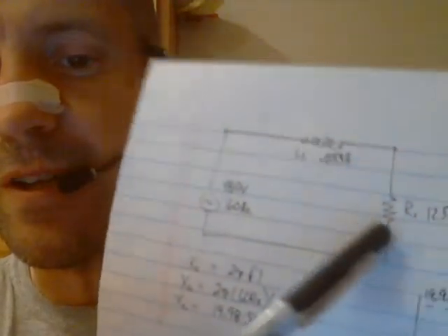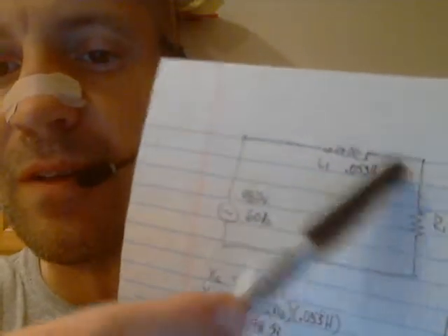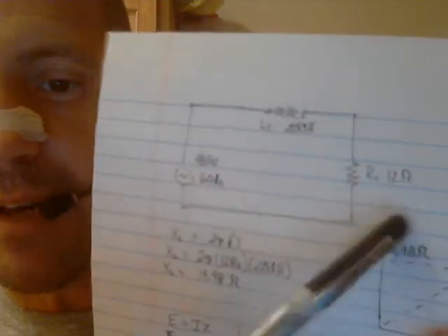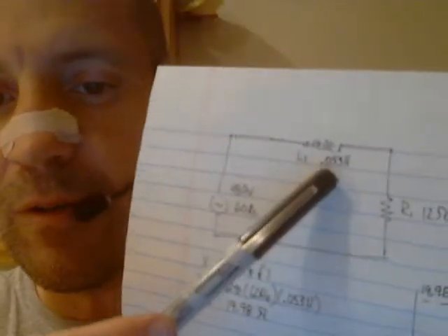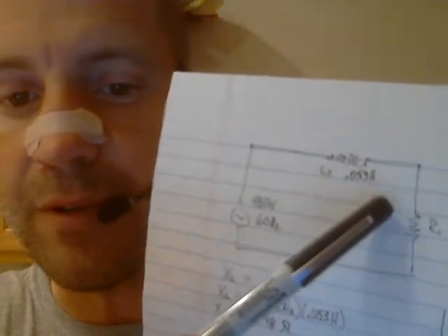We have to take into account that this resistance is occurring in one direction that is 90 degrees off, or leads the opposition to current flow that's exerted by our coil. So let's see how this works. I'm given the resistance in this circuit. I know that the resistor has a resistance of 12 ohms, but the only thing I know about my coil is that it has an inductance value of 0.053 henries.